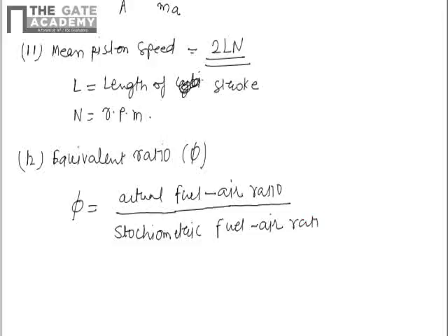The fuel air ratio during the operation of the engine will change. It depends on our application. For cold starting or idling, we have a high fuel air ratio. But for the economy zone or when the speed is maintained, we have the chemically correct fuel air ratio. And during more power generation, we require a higher fuel air ratio. So on the basis of that, we define the equivalence ratio.